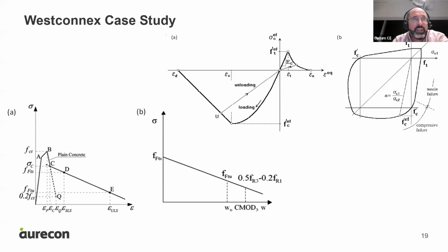The strain is calculated by the characteristic length of your element divided by the crack width that you are trying to calibrate against. So, for example, all these strains that you see in this slide are related to a crack width and a characteristic strength, which is dependent on the model. So yes, you're correct. We have to be careful that this is adjusted for your element size. Every single time, we have to adjust, and there's always a process of calibration. Then when you go to your real model, you have to use compatible element sizes. So there is an element dependency here, indeed.